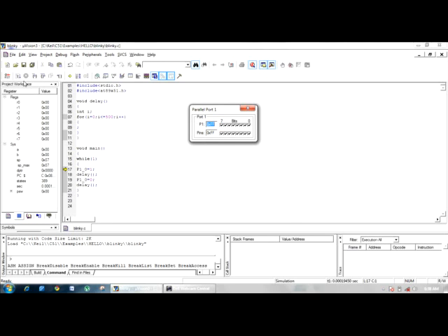Take the cursor. You have a tab here titled run. Click run. You can see that the 0th bit of port 1 is blinking alternately. So probably when you connect an LED to this 0th pin of 8051 port 1, you will have the LED blinking like this.